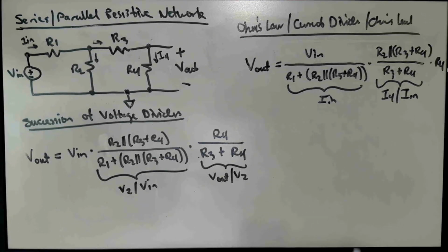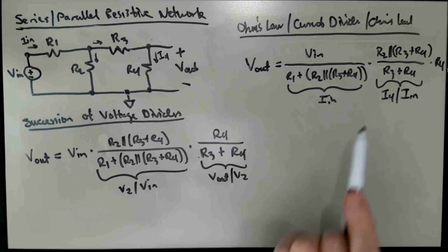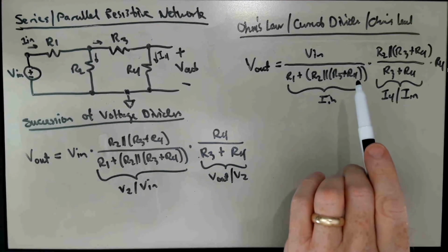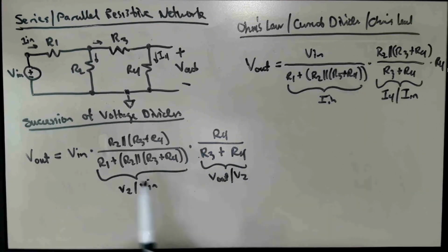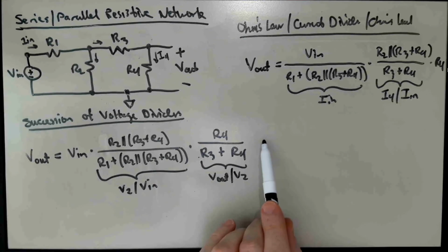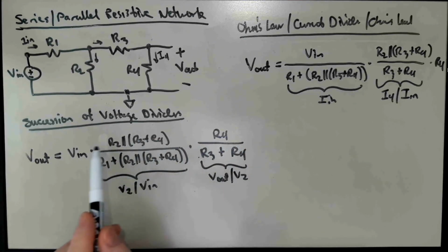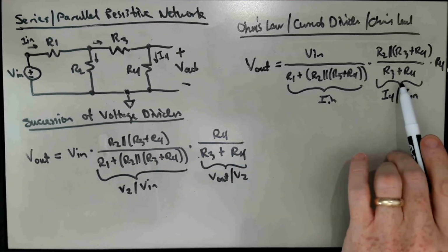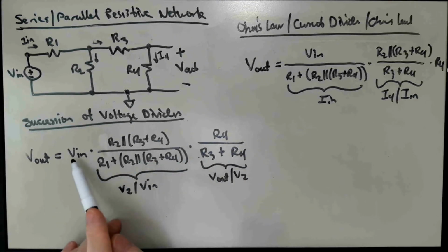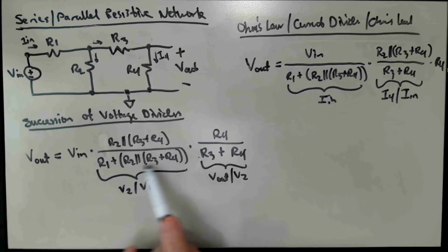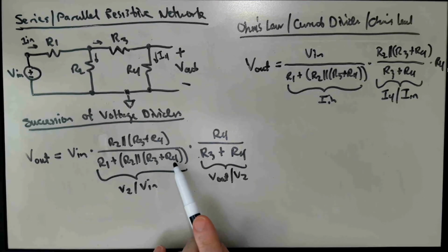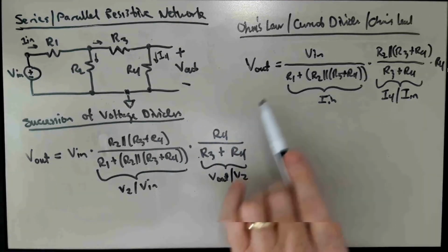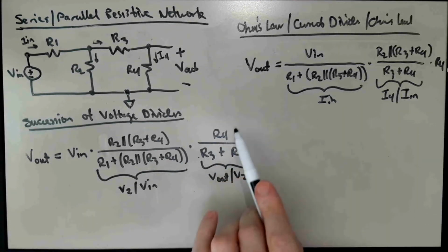And it so happens that by just shifting things over here, it's very readily apparent that these two alternative ways of arriving at the answer are exactly the same, right? So if I move the R4 off here and I move the numerator in this voltage divider ratio over here and group it with the R3 plus R4, I get my current divider ratio. If I move the Vin over to the numerator of what's left of this voltage divider ratio, I just get my original Ohm's law input current. So it's readily transparent that these two are equivalent to each other.